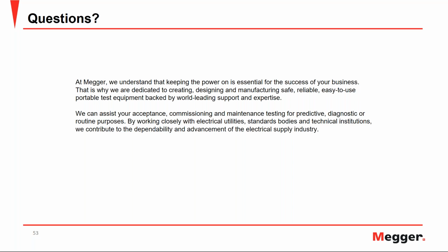However, as we saw during the presentation, the power factor testing has some limitations. When you have a power factor result that is increased, or that we detect a trending issue, or the values are increasing in the trend, then the outcome is always investigate. So we have to always further investigate. And at a certain point, determining that investigate is difficult, because of the limitations on power factor that we may not have